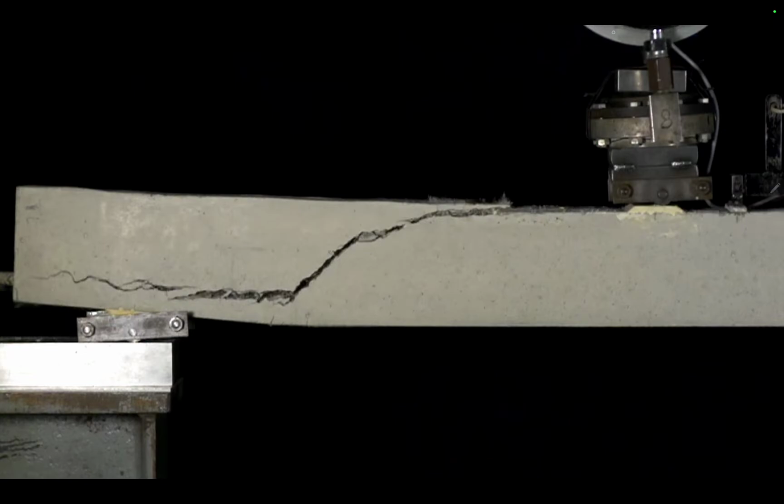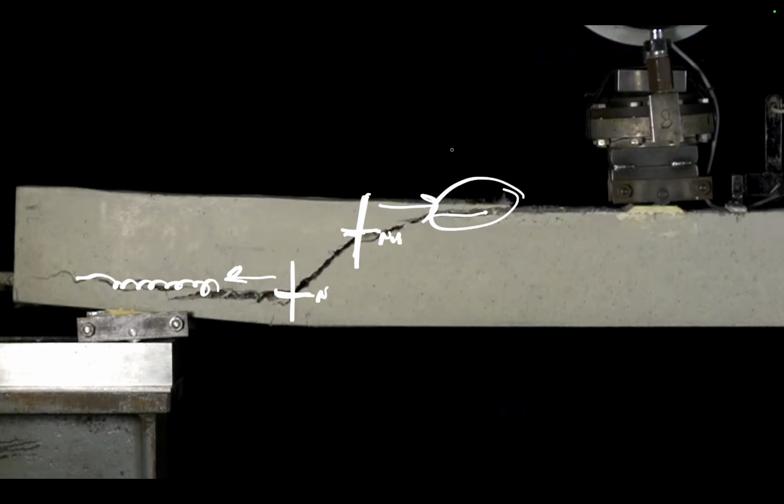So we get our change, our neutral axis here. We get our change of directions again, and you can see it now. So these are our neutral axis points where we change directions. Forces were only resolved here in the rebar this direction. Once it's split out here, that was done. It's completed task, only being able to resolve itself down here in steel.